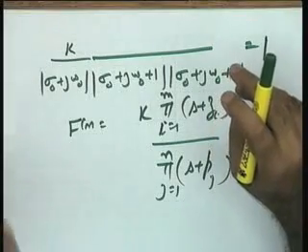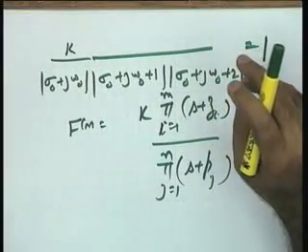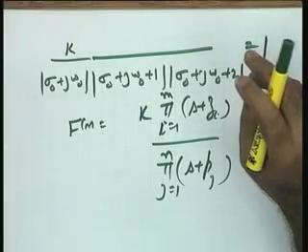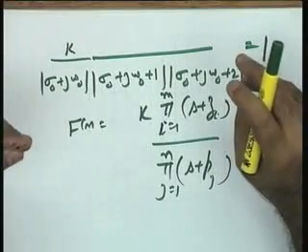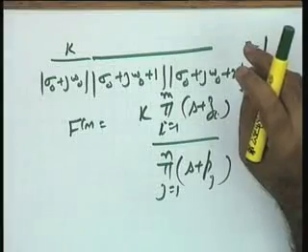So the magnitude criterion is always satisfied for any point on the S plane, but it does not mean that any point on the S plane is a point on the root locus, because both the magnitude and angle criteria are to be satisfied. Can we make a similar statement on the angle criterion, that all points satisfy it? The answer will be no.